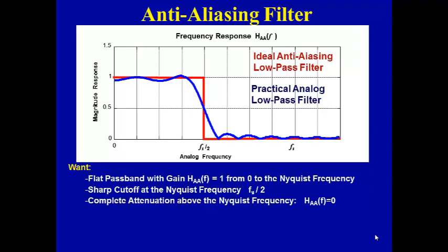Any ripple in the stop band means I'm letting signal through here, and I'm letting signal through there. I'm not attenuating perfectly. I'm letting stuff through that's going to alias. And because I can't make a super sharp cutoff, I'm letting this stuff through that's going to alias. And not only that, I'm throwing away stuff I was supposed to keep. So, not good. All right.